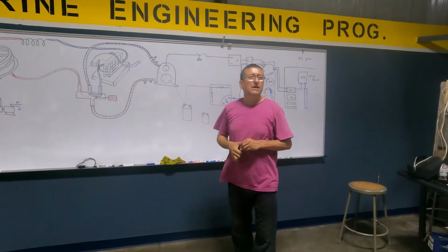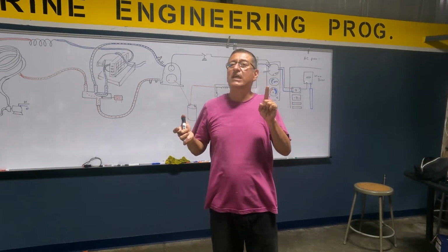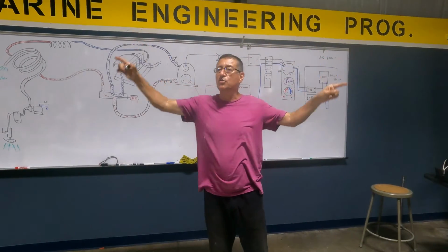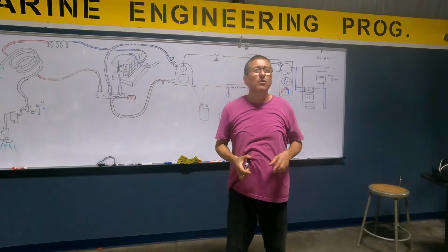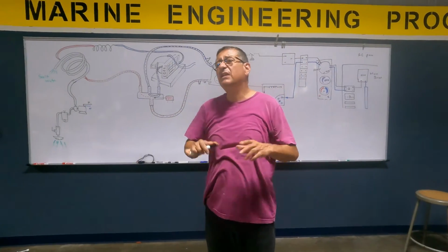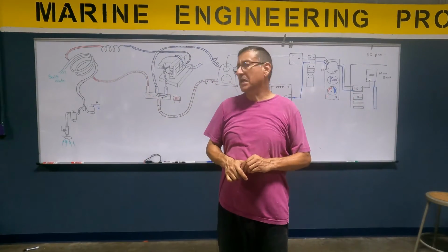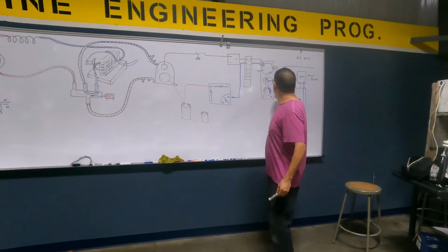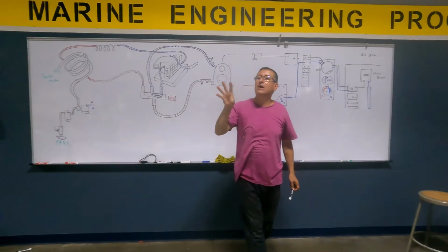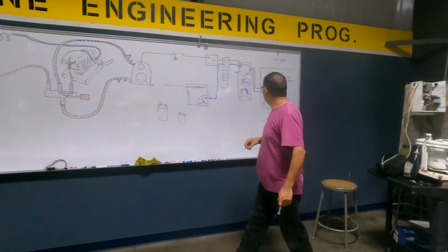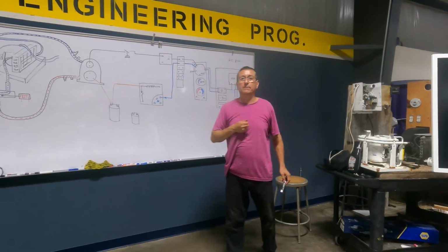Just the evaporator. Is only the fan of the evaporator. This is only to keep in your room mechanical ventilation, circulation of air. For what purpose? To keep the humidity distributed. Okay. Yes, mechanical ventilation is the fan. What fan? This fan. The fan of the evaporator. That fan working, running all the time. And of course, the third position is off, to turn off the system.